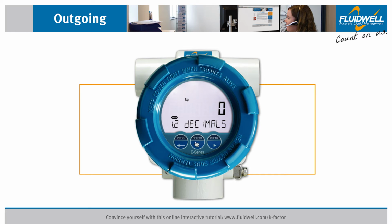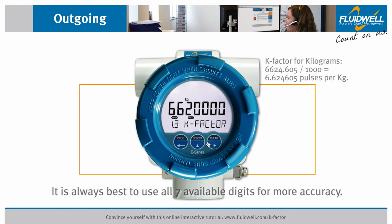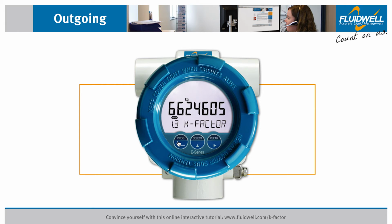Use Select to go to Menu 1.3 K-factor. Press Prog to set the K-factor. We are going to set the K-factor to 6.624605. The amount of decimals is not set yet. Press Prog to store this setting.